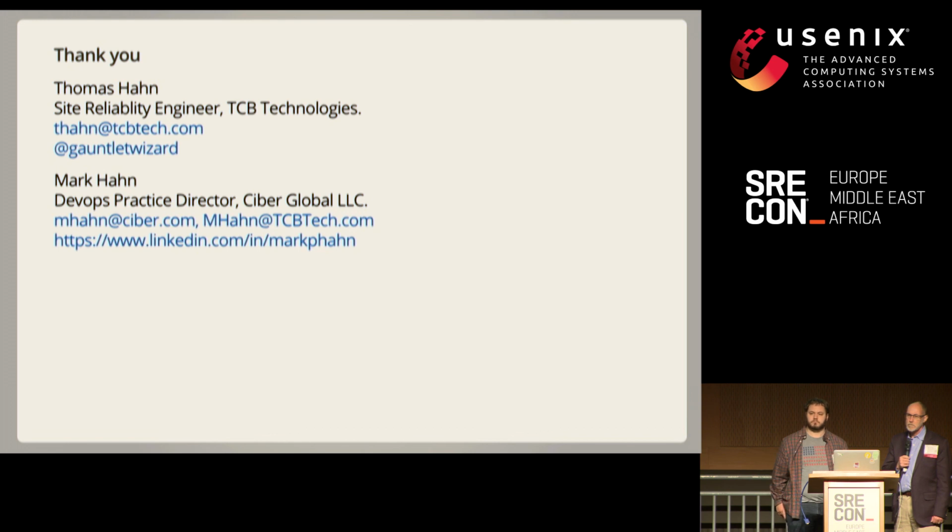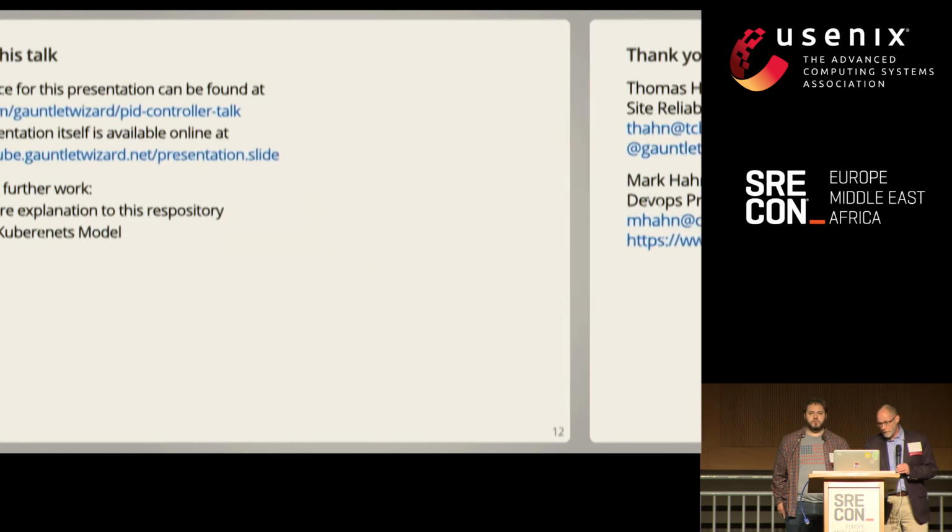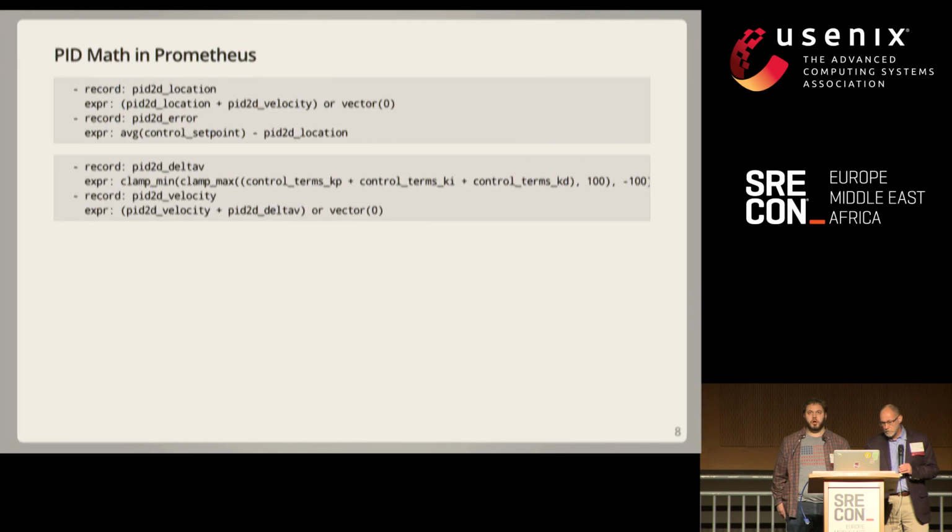Well, do PID controllers work when you have multiple sensors rather than one? The resolution is much harder to get right when you have multiple sensors. It does rely on the assumption that you have a relatively uniform output value. It only has one process variable that is measured.